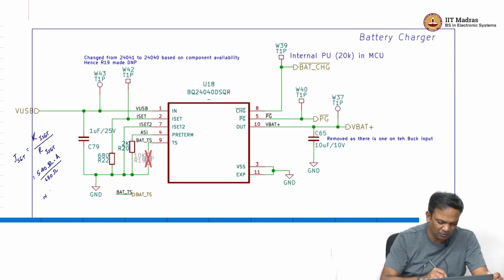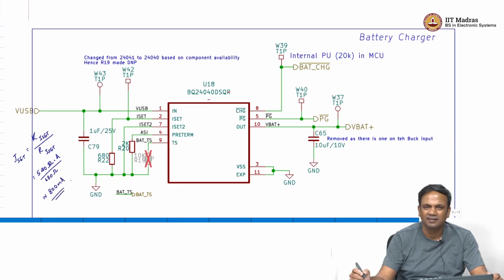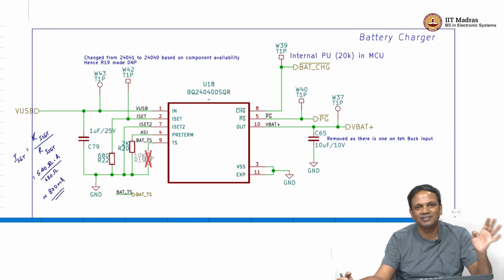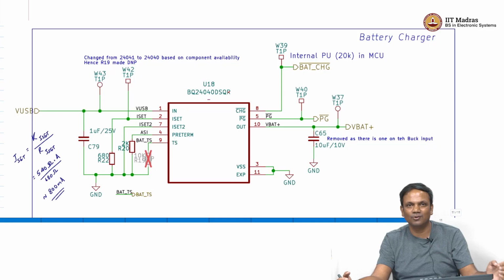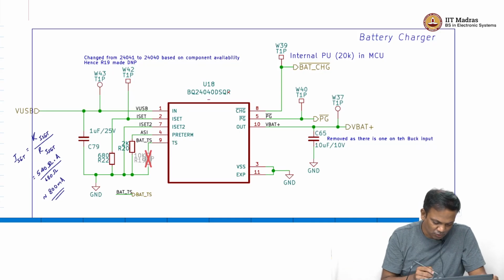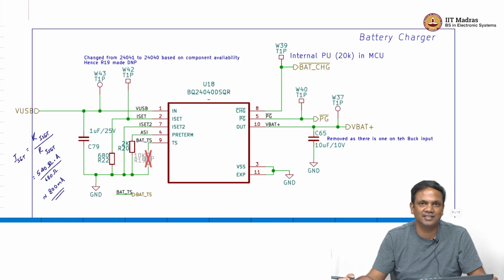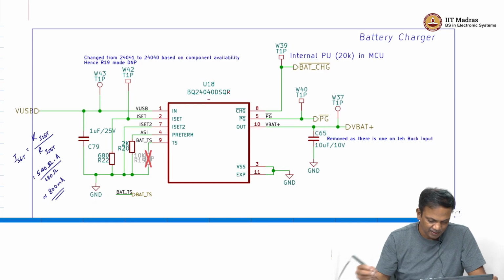This is about 800 milliamps of current. In our application we decided to go with a fast charge current of 800 milliamps. It is just knowing how these calculations are done. So, R22, in our case 680 ohms, determines the amount of fast charge current that you will get.